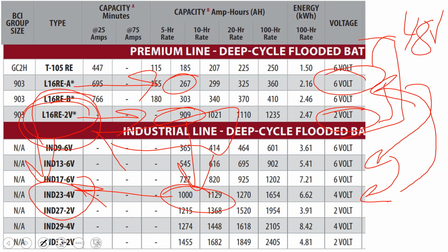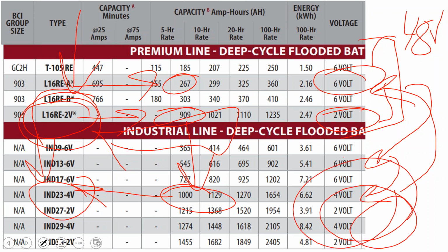And so if I'm doing the hippie retirement plan, buying cheap land in New Mexico to go build my little off-grid prepper community, I would be going with the lighter weight battery and installing multiple batteries because of transportation issues. But if I'm doing an off-grid home where we already have some offloading equipment on site and we can just take a giant heavy battery bank with a battery crane and drop the batteries right in place, then you might get into slightly more cost-effective industrial batteries where you only have 8 batteries for the entire system instead of 48 batteries. It's just that they're much heavier and harder to manage.